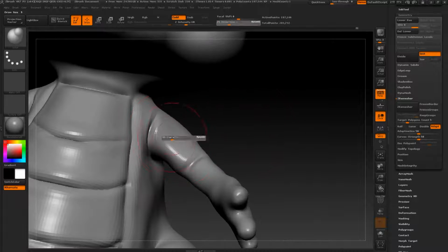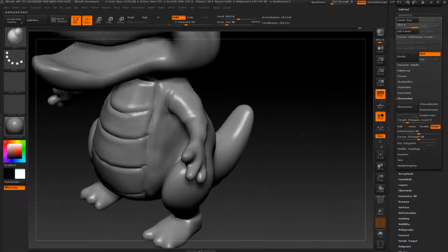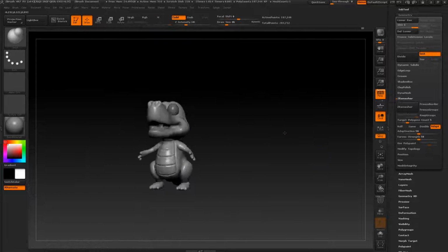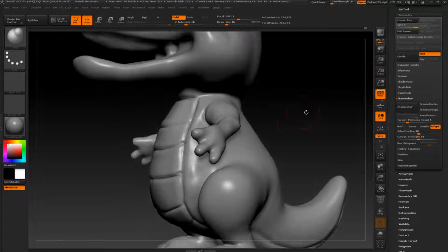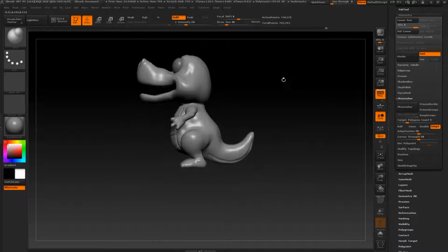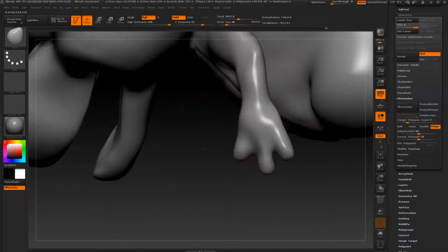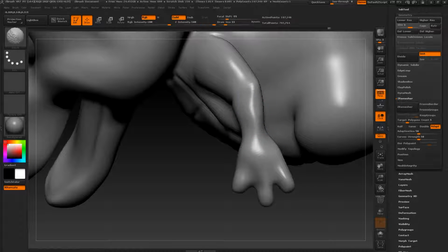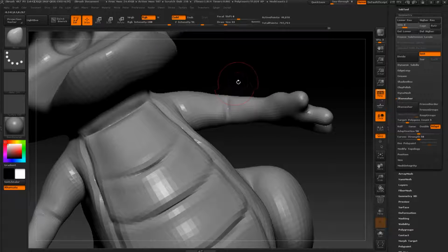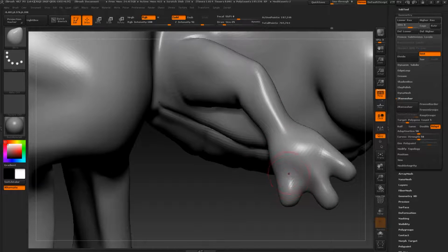Let's add some shape, smooth. From now on it's a long process of adding and smoothing until you like your result. Let's add more subdivide. When I do not need the subdivide, I just press Shift D and I will decrease it, and with D on the keyboard you will increase it. So it's a good shortcut.